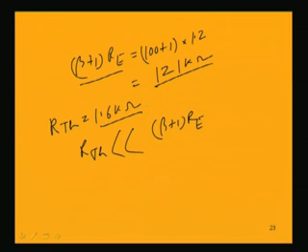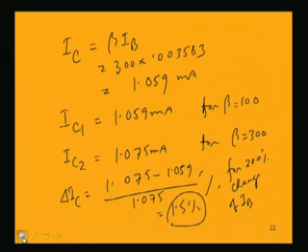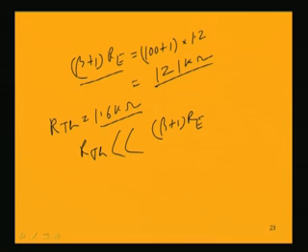That is why IC is almost insensitive to beta. Even though beta is changing so much, a 200% change, we are not having a correspondingly high change of IC, and that is the beauty of this design scheme. We make it possible by this design criterion being satisfied.